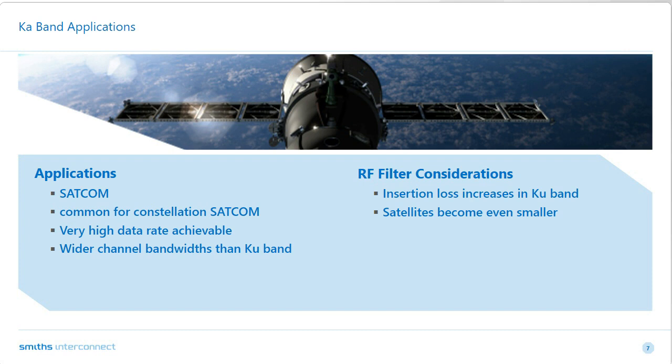They both allow for data rates in the terabits per second and are used commonly in the low Earth orbit constellation satellites. Ka band leads to smaller antennas as well. When considering satellites operating in this frequency, the constellation satellites typically have a lower life expectancy and are more cautious to cost. One way of reducing costs is to reduce the screening and qualifications required. The trade-off of the benefit of full screening against the cost savings of limited or sample screening is more common